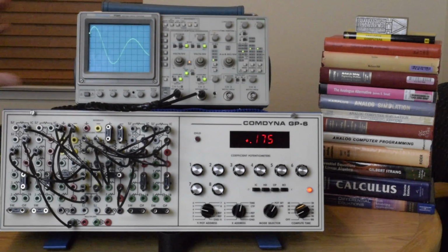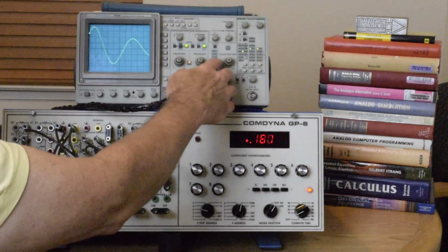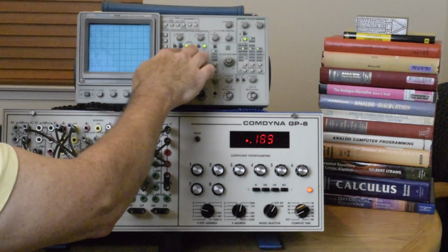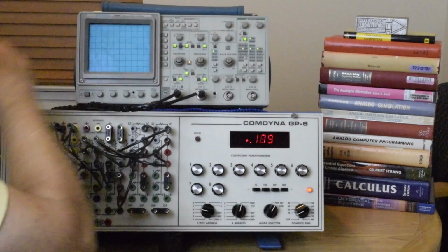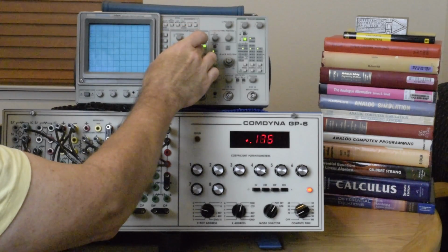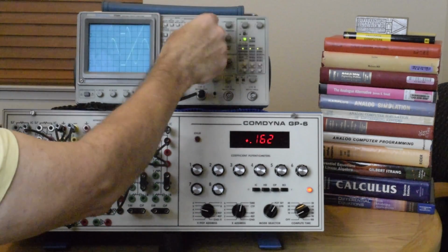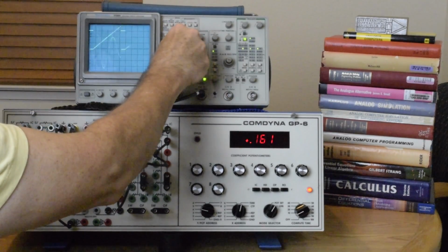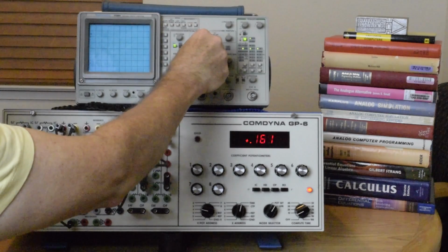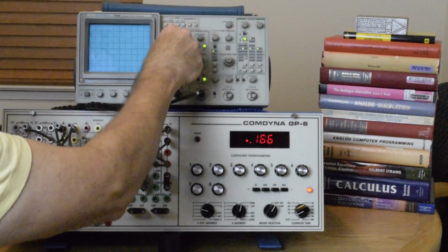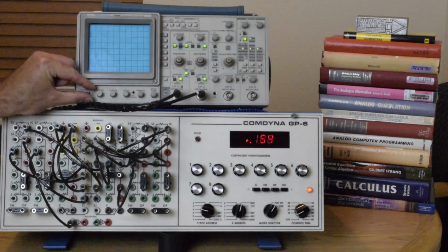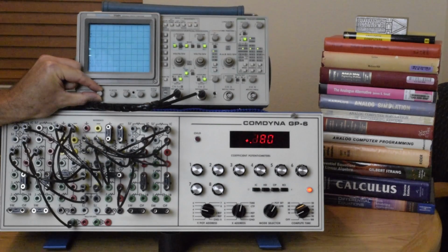Well, so that's how it would normally be displayed on the scope, but if we look at the scope in normal, what we call YT mode, and then look at both channels, you'll see what the actual analog computer is outputting there. And then what I'll have to do is set these both back to calibrated and reduce that. So here the sweep is a little slow. I'll bump up the intensity a little bit so you can see that a little better.